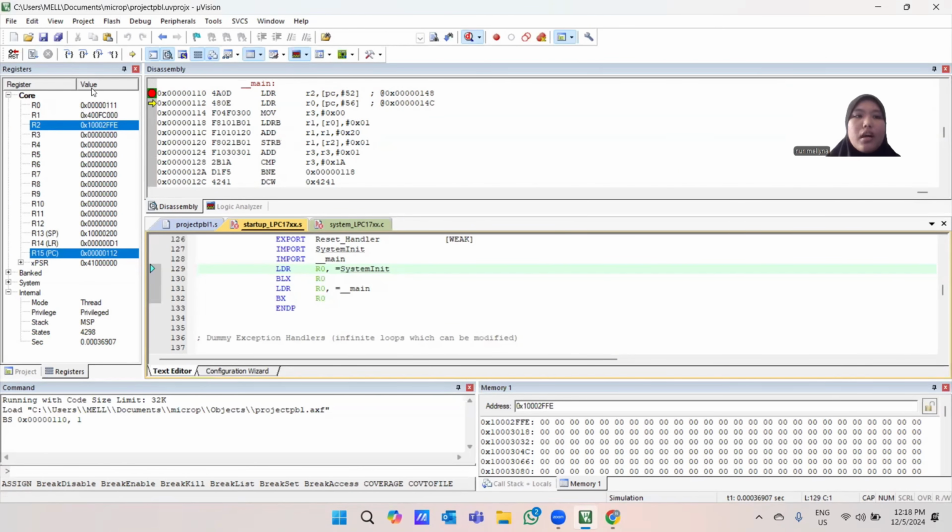So we are going to run until 26 iterations. So it has been 26 iterations, maintaining the loop counter. So the loop counter will be 1A. The last address is 3018, and the last data that has been stored is 7A.